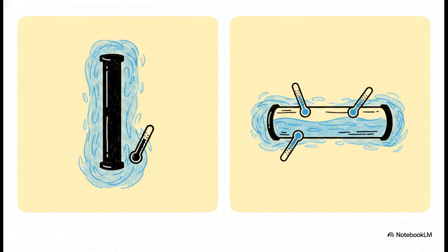And here's a really cool detail. If a purchaser specifies a design metal temp that's lower than the highest of those two fluid temperatures, that specific lower design temp literally has to be permanently stamped right onto the manufacturer's nameplate.